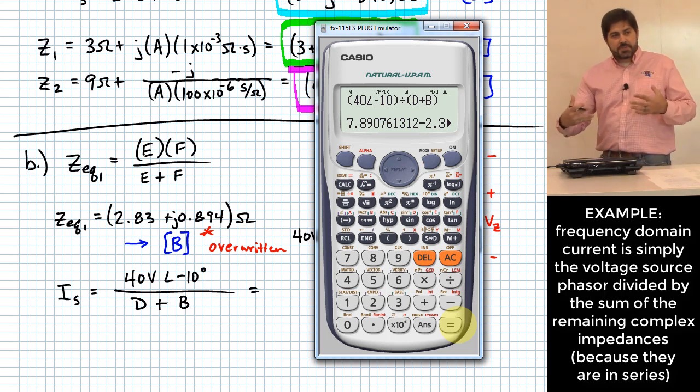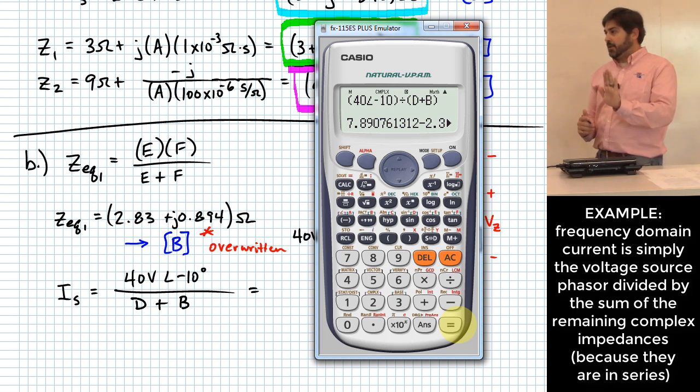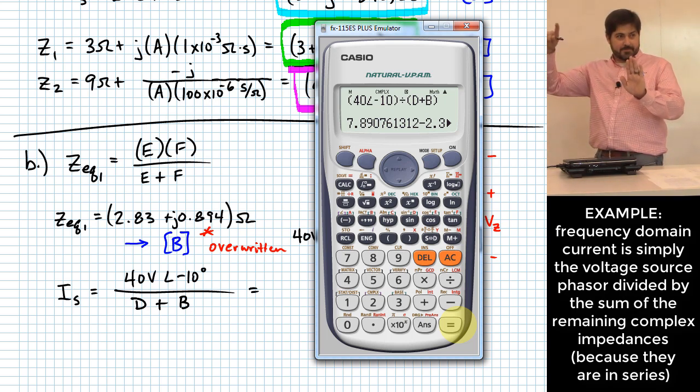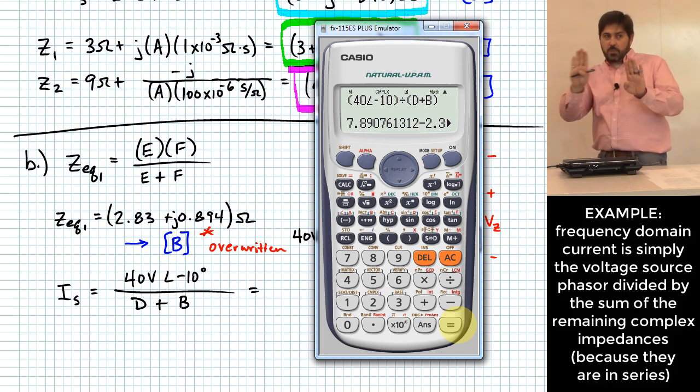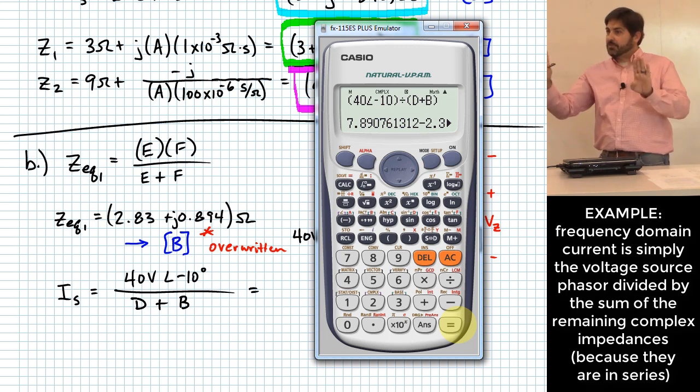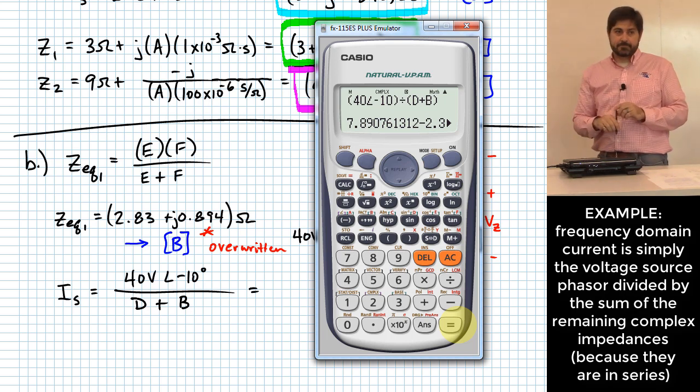It has more physical meaning to me, right? The amplitude value in polar form is the size of the wave, and the angle value is how far that wave has shifted relative to 0 angle. So it's how far it is shifted, and you can use that relative to your other values to know how the waves might set up next to each other in terms of time.